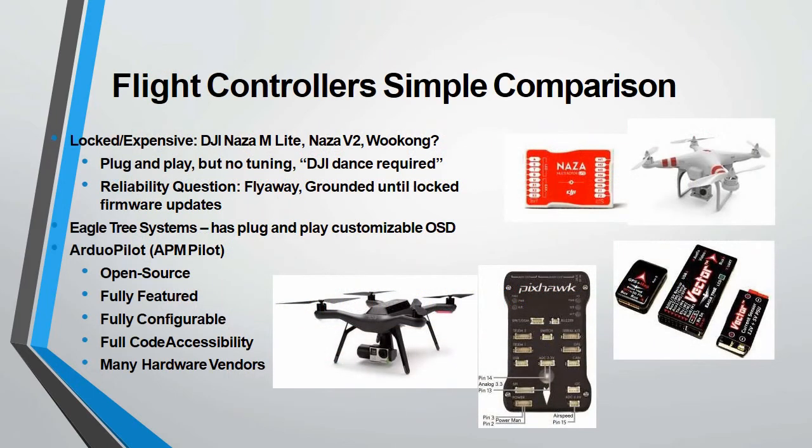Now for flight controllers, here is a simple comparison I have given. The expensive DJI NAZA-M Lite and NAZA V2 and Wookong are plug and play but with no tuning in this. So DJI is locked down. Reliability questions: flyaways, grounded until unlocked, firmware updates. Next is the Eagle 3 systems, which has plug and play with a customizable OSD. And then ArduPilot, APM, is open source, fully featured, fully configurable, and has full code accessibility. Many hardware vendors are also there in it.